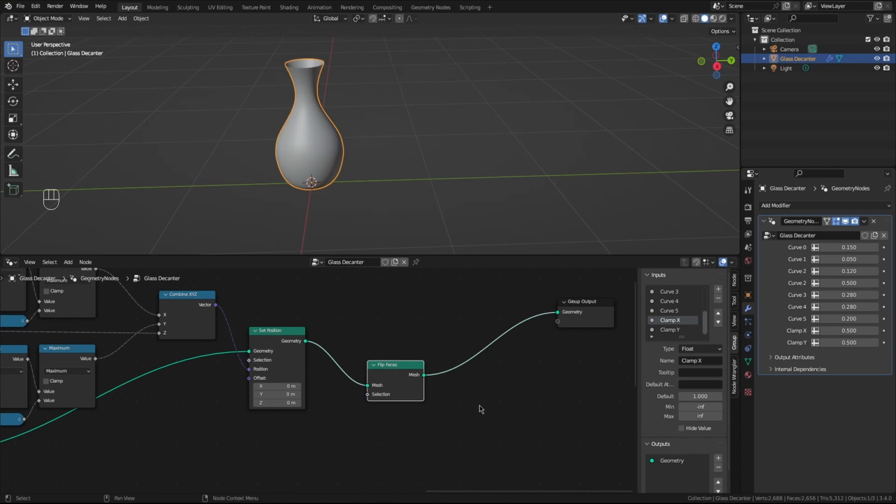Now I don't really care which way the normals are going, but what I do want is the surface normals to be pointed out from the glass object. So by doing this, the normals on the inside of the container will be facing in, and the normals on the outside of the container will be facing out. This is the only way to get the glass shader to work properly. If I didn't do this, you would actually get a 3D container, and it would look great, until you rendered it. And then the interior reflections in the glass would do crazy things. For one thing, they completely obscure the inside of the glass, so you won't see your liquid at all.